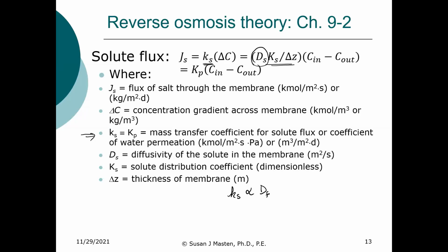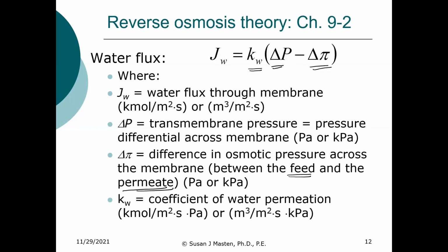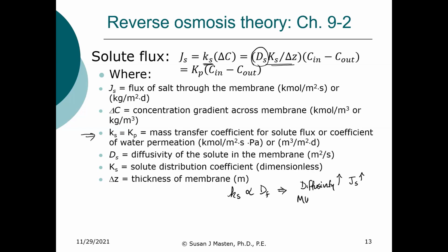So that means as diffusivity increases, the flux of your salt increases. What does that mean? Solutes that typically have a higher molecular weight will have a higher diffusivity. Oh, sorry, will have a lower diffusivity. So as molecular weight increases, diffusivity decreases.